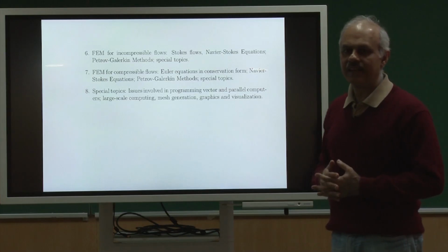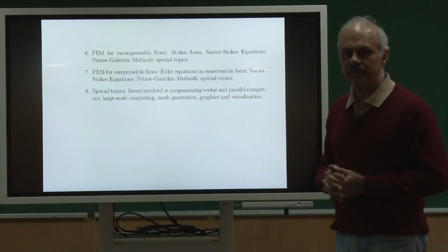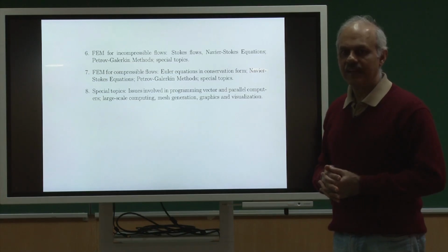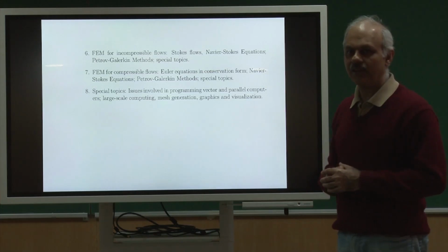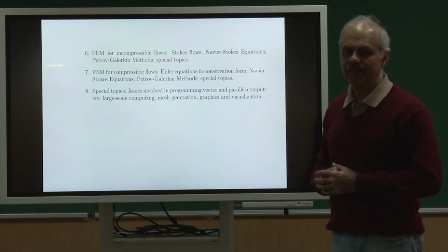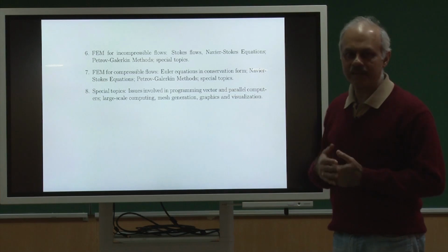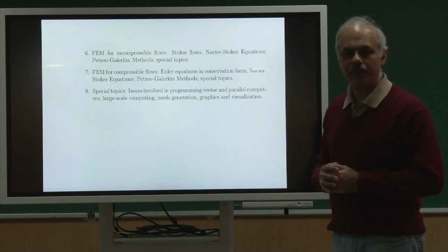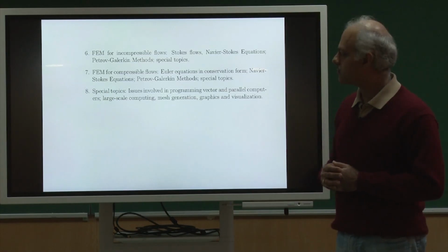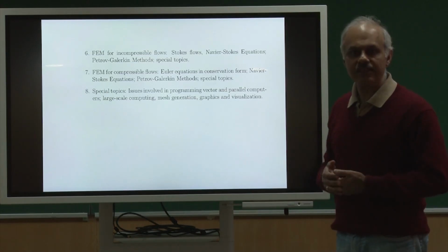If I am using, let us say, second order terms for velocity, and I try to use a second order approximation for pressure, you can see there could in principle be some problems because the order of derivative is different for the two. So then how do we deal with that?